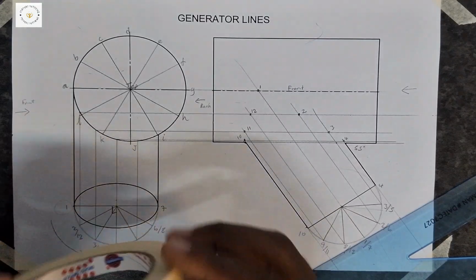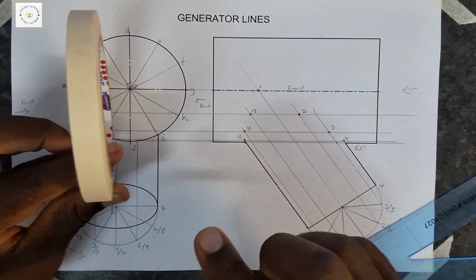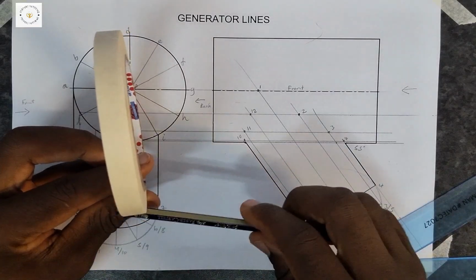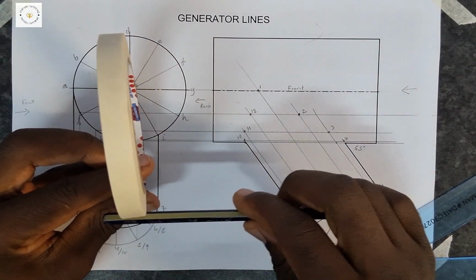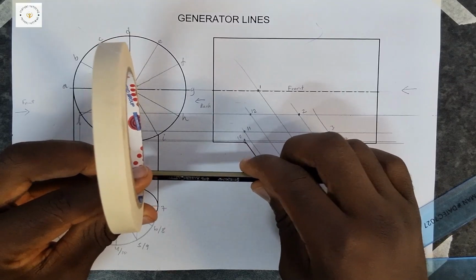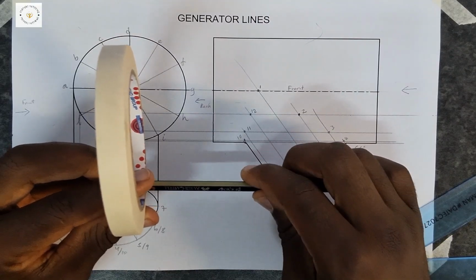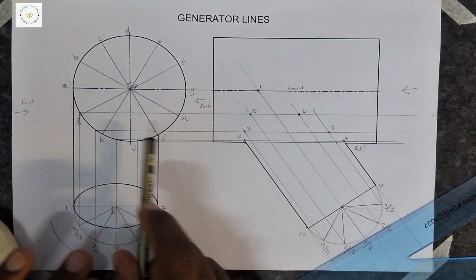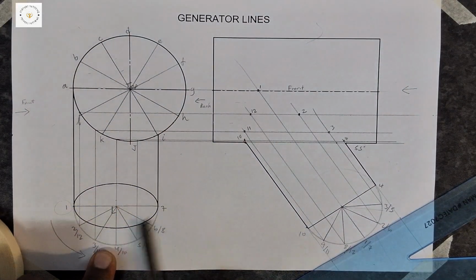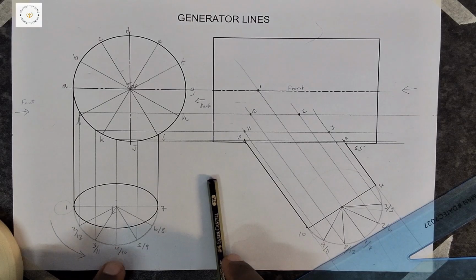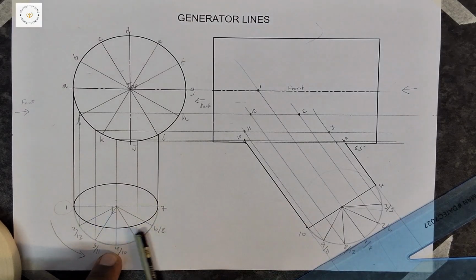So I cannot see on the other side. Which means that, for example, if you were looking at this thing, this in your case would be your 4. You cannot see what is on the other side, right? So if you can't see things on the other side, we call those a hidden detail. So whatever I'm drawing from 4 going this side, those will be hidden details, right? I hope I make sense there. So those will be our hidden details.